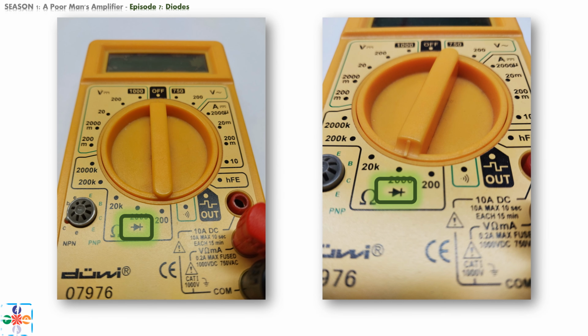Now, let's see how we can determine voltage drop by using a multimeter. On your multimeter, try to locate this icon. Depending on the type of multimeter you have, it may be at another location, but in general, every multimeter has this option for selection. When the selector is in this position, it allows a small current through the diode and measures the voltage drop across the diode, against a predetermined voltage.